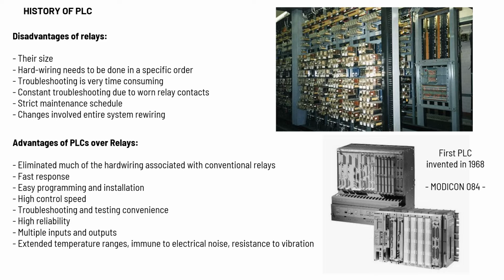Advantages of the PLCs over the relays. They have eliminated much of the hard wiring associated with conventional relays. They have fast response, they are easy to program and install, high control speed, troubleshooting and testing convenience, high reliability, multiple inputs and outputs, extended temperature ranges, immune to electrical noise, resistant to vibration, so it means that they can be used in any industry.